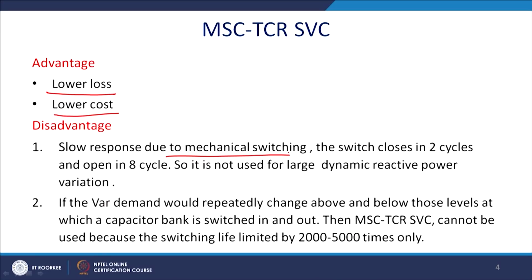So, the advantages are low loss and low cost, and the disadvantages are definitely more, because it is used in practice before the FACTS devices. There is slow response due to the mechanical switching; the switch closes in around 2 cycles. So, for this reason we require to insert this reactance very slowly, and this leads to subharmonic oscillation, and it opens in 8 cycles. So, we have to gradually dissipate the power and open it.